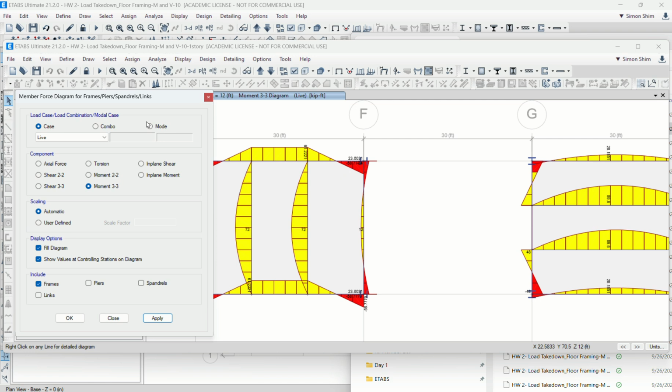So for wood, you need to be much more specific, because steel and concrete are engineered, so we come up with more consistent weights. When we build the structure, our concrete and steel weight is pretty much consistent. But with old wood, people used different wood here and there. Wow, their weight is different. Capacity is different as well.